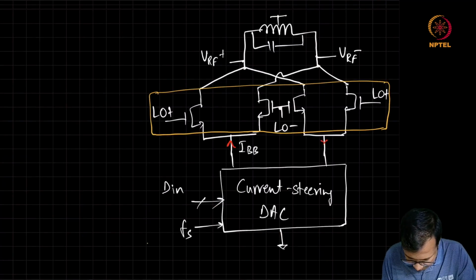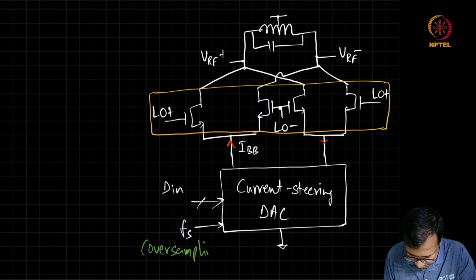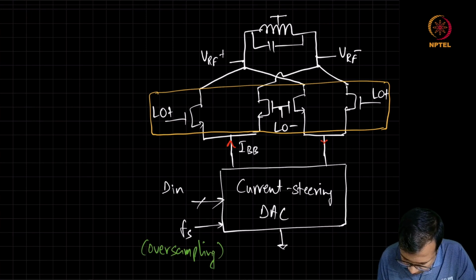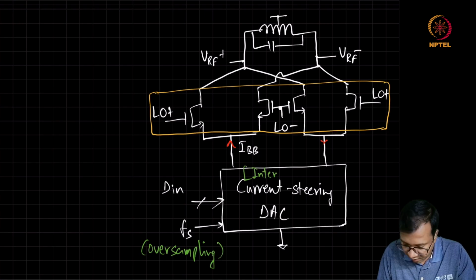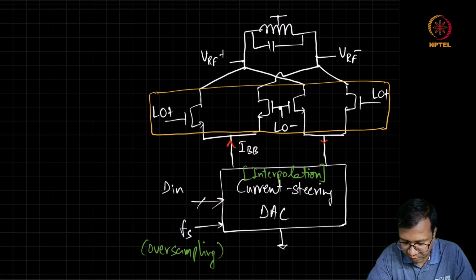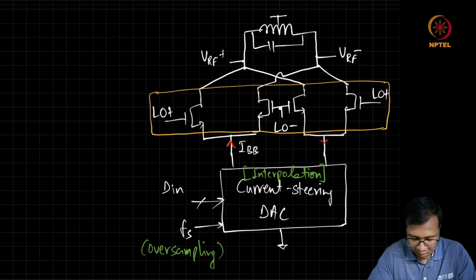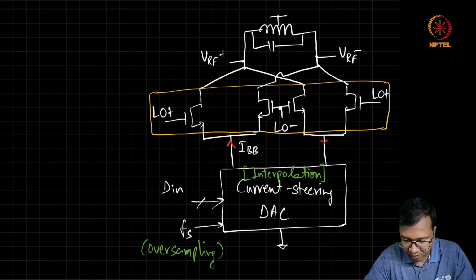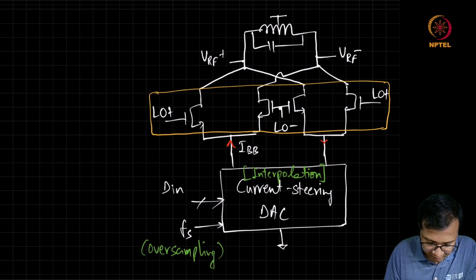So here we can do oversampling as well as better interpolation than just zero order hold. And one case we have already seen with the help of L-fold interpolation. So together, it is possible to keep the DAC images below the spectral mask.